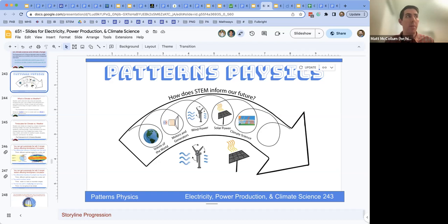If you do this, I would suggest going and testing it wherever you're at. For example, we have a courtyard area, but our courtyard has really bright concrete around, and some of that reflected light off of the concrete hits our solar panels and throws off the data a little bit.